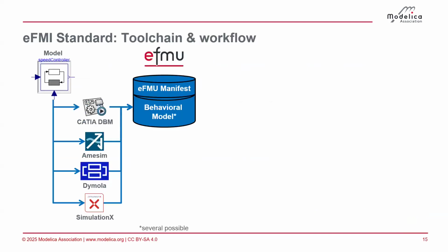And the workflow is roughly like this. You would start from your model. It doesn't necessarily have to be Modelica, but the tools we have at the moment are from the Modelica world, but other simulation environments are invited to support eFMI as well. It's not dedicated to the Modelica language. And there you could generate the behavior model from your offline simulation, where you define, okay, this is the test scenario that must be satisfied. These are all my scenarios where I will test my controller. Then you generate the algorithm code. And then the simulation environment world stops.